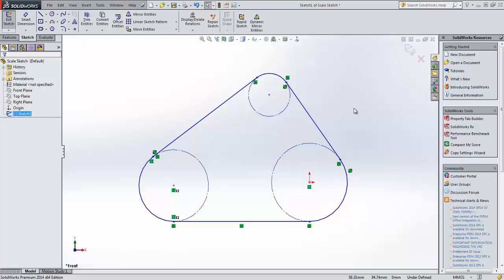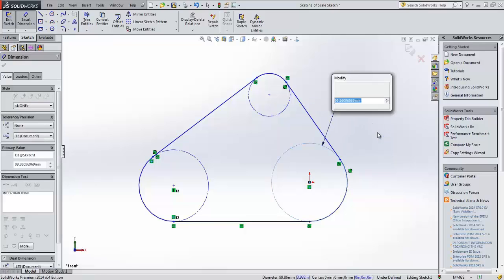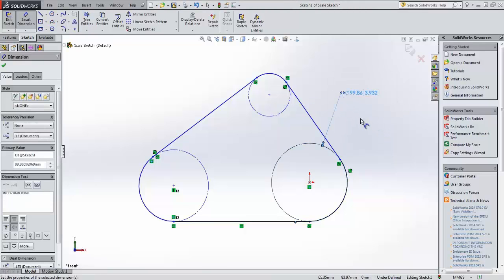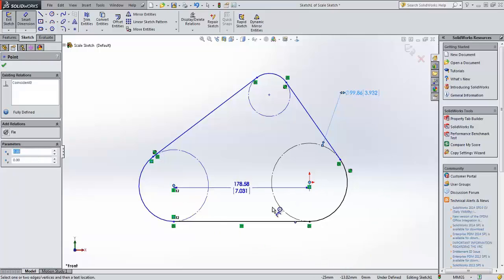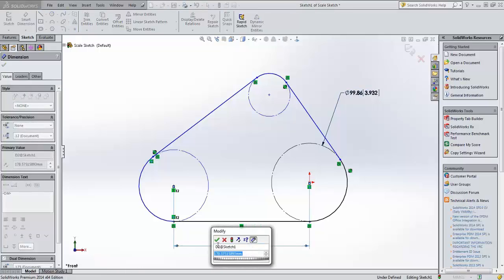or the sketch shrinks. However, SolidWorks has introduced a quick solution to eliminate this with an enhancement that you don't even see happen. So now if you go ahead and put in the first dimension, SolidWorks will automatically scale the entire sketch to that first dimension. Once you've added that first dimension, everything else goes back to how it was before, and you can dimension everything to scale.